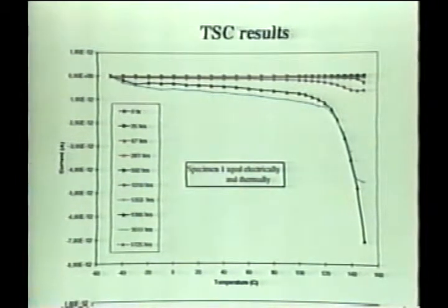After the 50 degrees Celsius aging of this specimen, we increased back the temperature to 120 degrees C, and the resulting current measured after that aging step with TSC had lowered to an intermediate value compared to the 2 previous curves and everything that was measured before. This indicates that there are some changes occurring in the material, but after only a short exposure time, it does not appear that those changes are permanent.